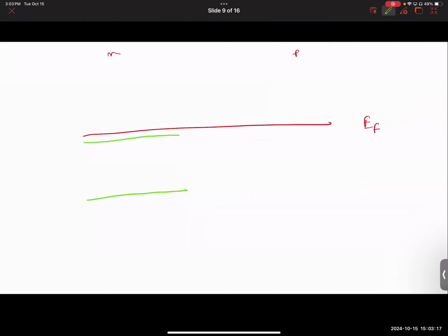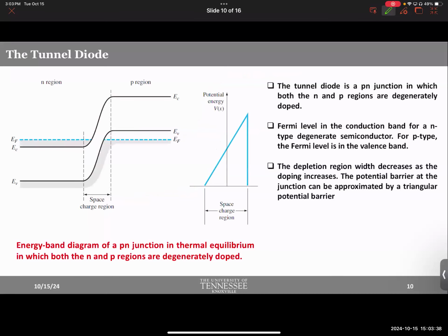So this is N plus. And then for P plus, we'll draw the valence band above the Fermi level and then the conduction band. And then we'll add them really nice, with nice and smooth curves to represent the gradual potential change. All right, so that's what you had here. Any problem so far? Okay, and just, I mean, this is a side note.